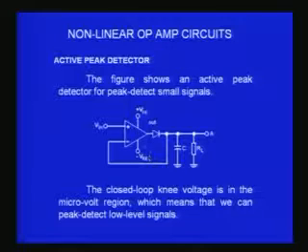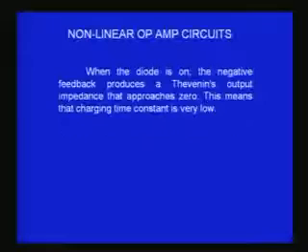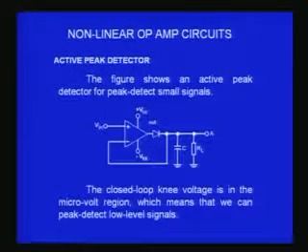So here again you can do the peak detection for very low level signals less than 1 volt. You can comfortably convert them into peak voltage and then measure using a normal multimeter or DC voltmeters. So now I will perhaps show you the peak detector on the demonstration lab. I have a demonstrator board, and then I will come back and continue with the rest of the demonstration.